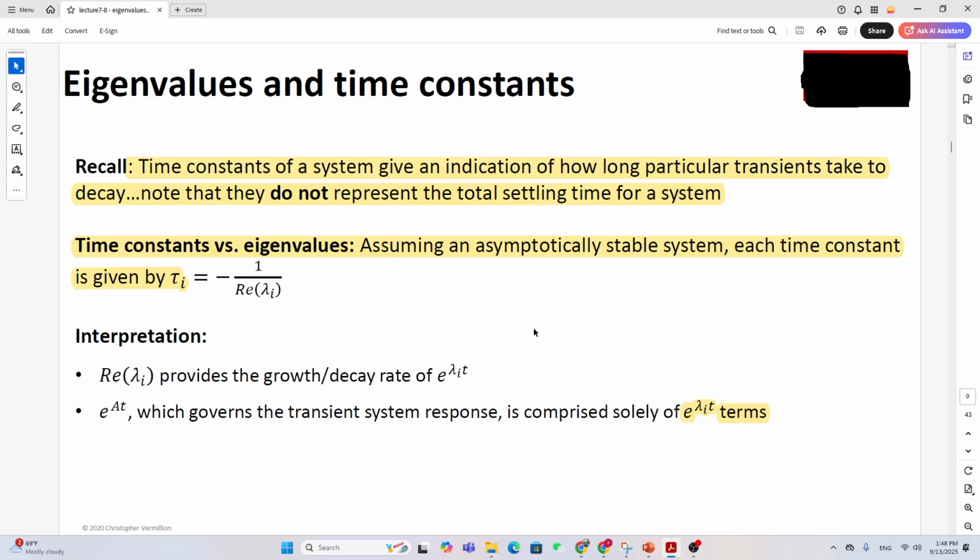If you have eigenvalues less than 0, removing the equal-to-0 term, you have not only internal stability but also internal asymptotic stability, right? If you have a term that is equal to 0 only, then you have a marginally stable system, which is not covered in this slide, but I want to mention it.